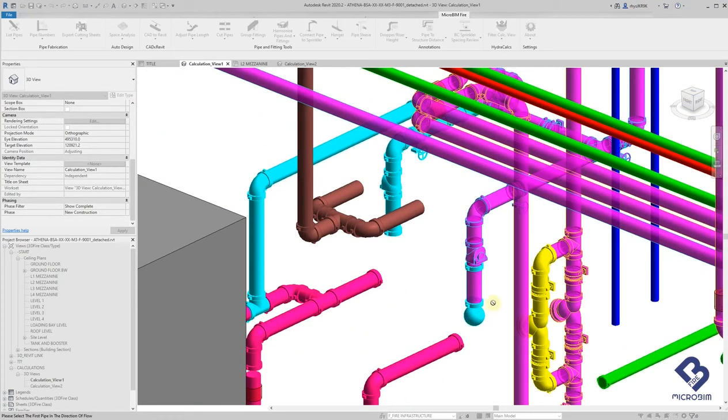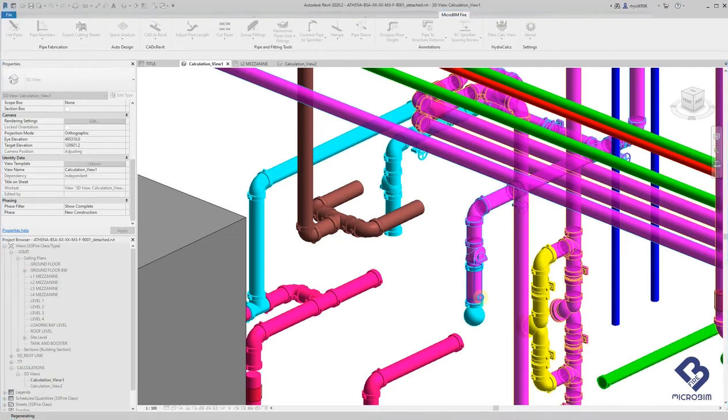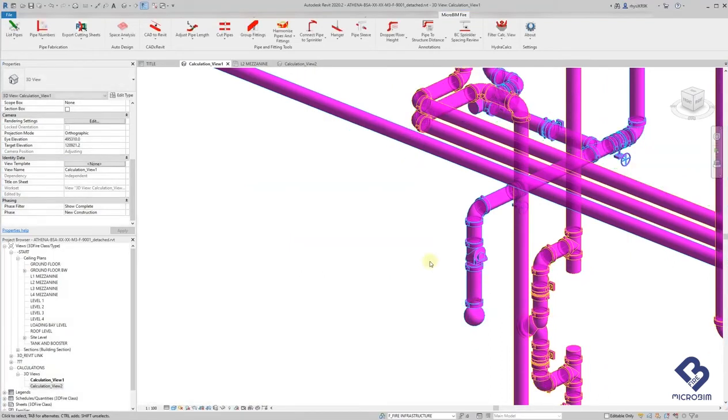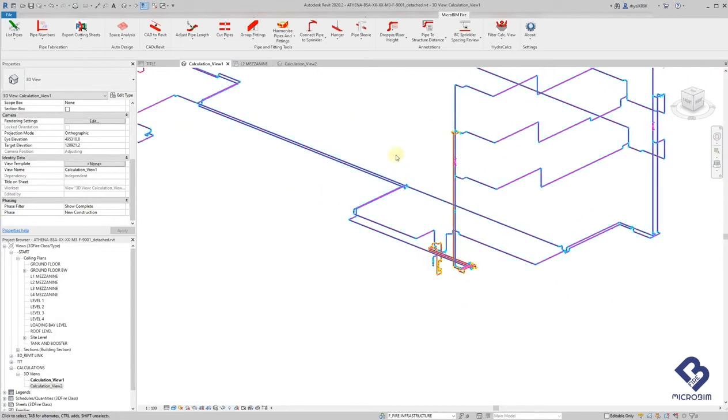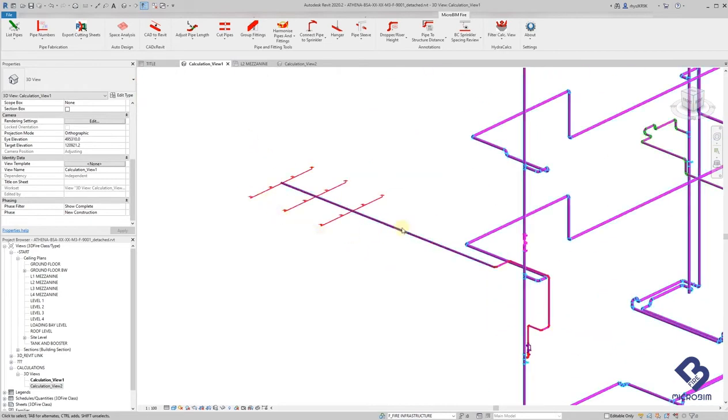Navigating to our water supply and the pump discharge, we select the start of the first pipe. This will then filter out all the unnecessary elements, pipe, sprinklers and hydrants that are not required for the area that we've nominated in order to calc. And we can see here that the filter has eliminated all of this unnecessary information. It's kept our hydrants, and there are our 12 sprinklers for operation.